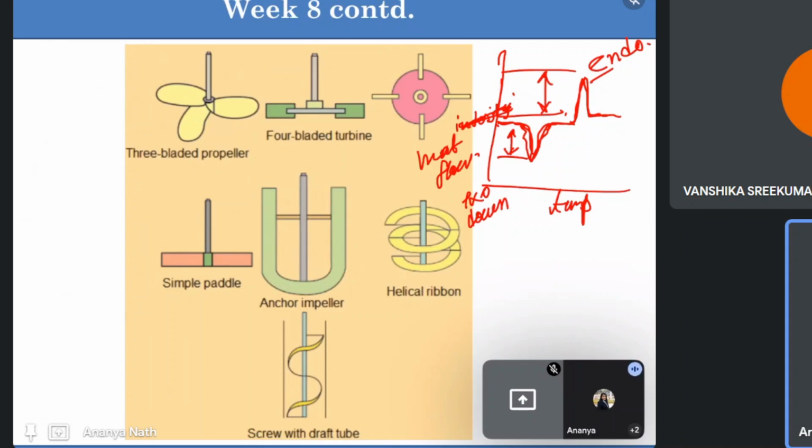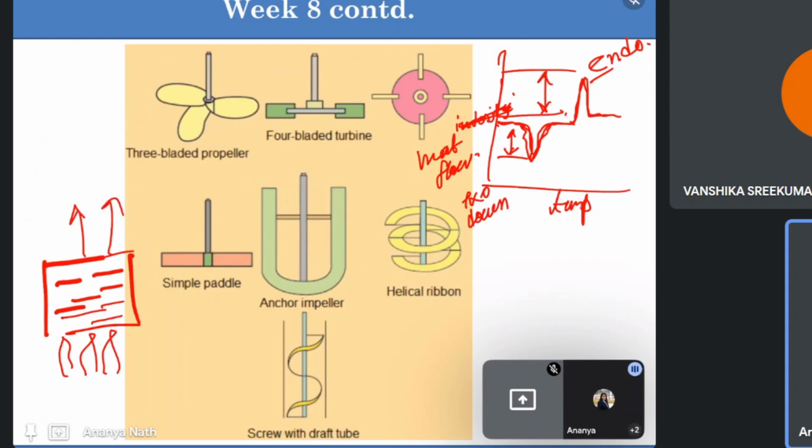Because if one material is having a lot of strain, means extra half planes of dislocation, and it's heated up, it's not that the heat is released at the first stage, there will be no strain, and this is recrystallized. That's not the thing. The recrystallization will take place by some other means. There is no direct relation between this strain release and recrystallization. Obviously, strain release will initiate the recrystallization, but it's not that only if all the strain is released can we say it's recrystallized, because recrystallization means there is no strain present. There are strain-free grains which are newly born.